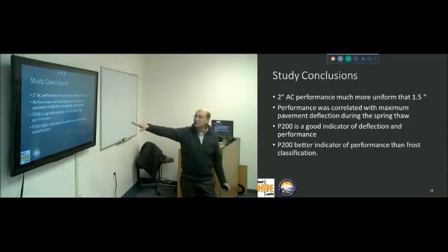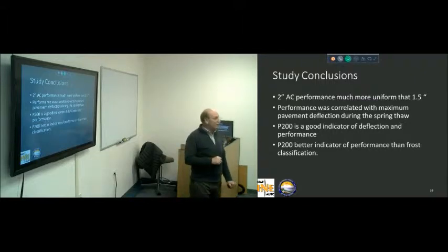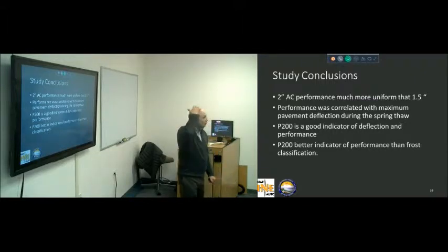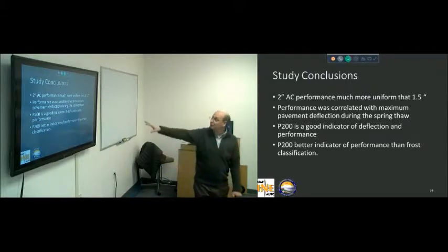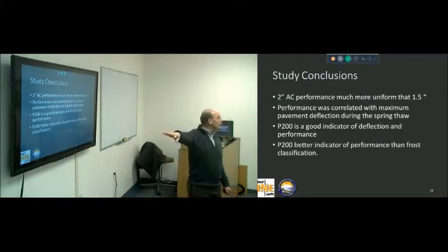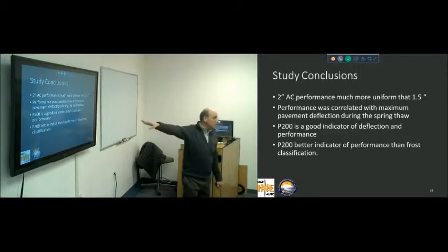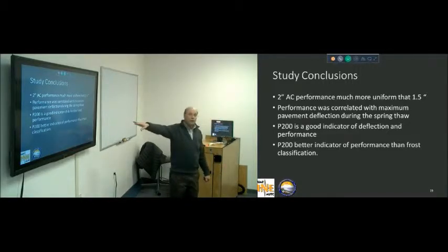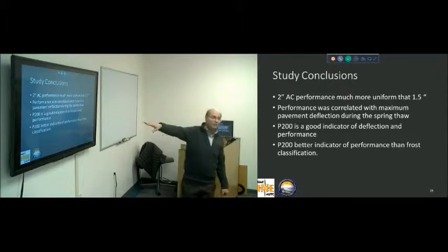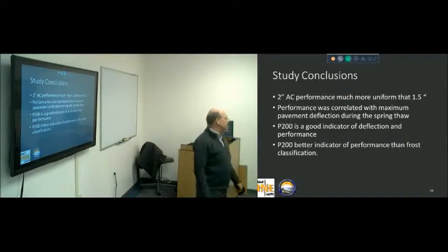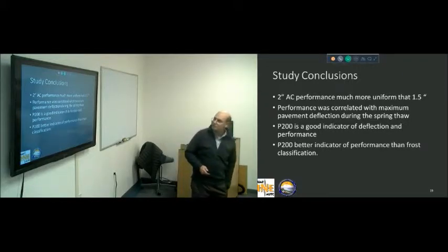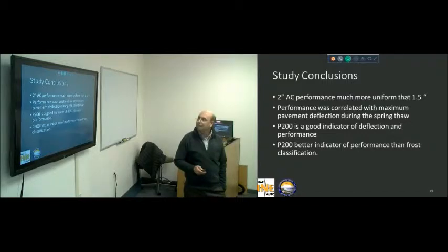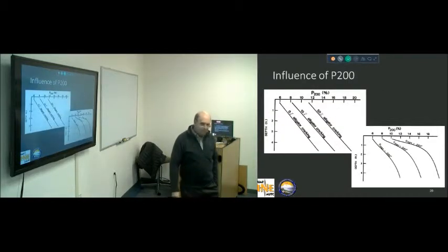The 200 sieve was a much better indicator than the frost classification or the frost heave test, which was a good thing because it's a lot cheaper to run than the frost heave test. But the frost classification really didn't correlate very well with our pavement performance. And so that's why you don't see the frost classifications in any of our design procedures. We just walked away from that and said we're going to focus on the fines content passing the 200 sieve and let that go.